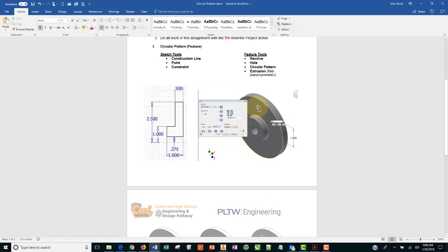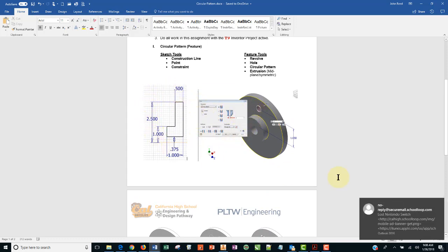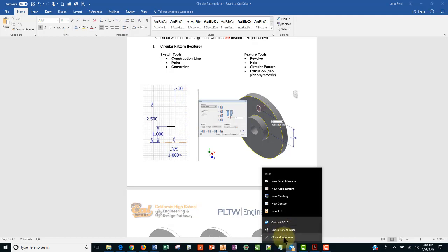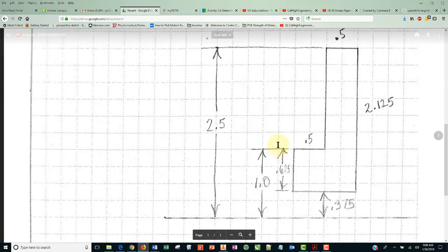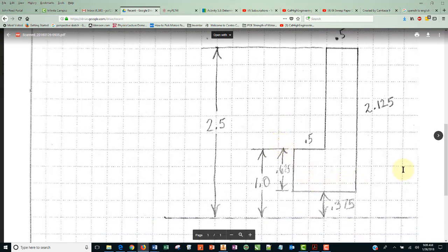And we're going to create the original disc using a revolve procedure, and this is the 2D sketch, and you can see down here our axis of rotation. Now these are the kind of sketches that I typically make mistakes on, so when I know I have to get this right, I just draw it out, and I believe this captures everything.